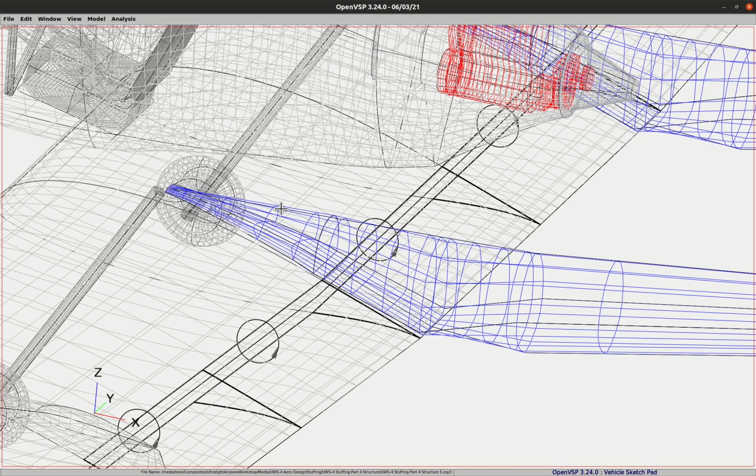So if I was going to make this sheet aluminum, that would be very difficult to carry those forces through here. The force up here on this one is going to be fairly significant in pitch. It won't be insignificant for lateral forces, but pitch will probably be the highest force. And this distance here isn't very significant, so there would be fairly significant stresses through this area also. So I decided not to do stressed aluminum skins in through this area.